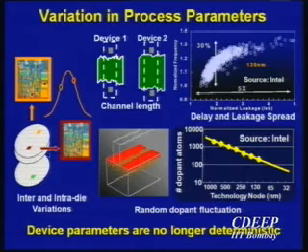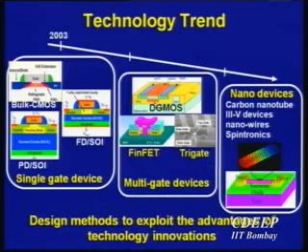Remember earlier I mentioned that the short channel effects are in general given by the aspect ratio of the device. The aspect ratio again is the vertical dimension to the horizontal dimension, right? Interestingly enough, if you have two gates rather than one gate, one top gate and a bottom gate for the device, and a very thin body, it turns out that device is going to be twice as scalable as the single gate device. Or in other words, I'm trying to control the flow of current from the source to the drain region by looking at two sides, and by trying to control the channel from two sides.